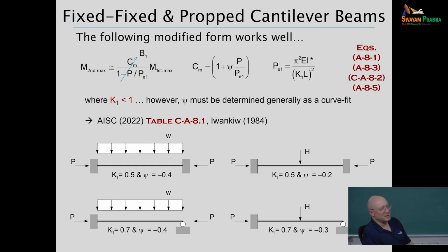That's because in the AISC specification we have something called the direct analysis method, where we reduce the stiffness to get a better calculation of the moments in the physical structure. I'll say a bit more about that as we move along, but it's really only the Americans that are doing that.